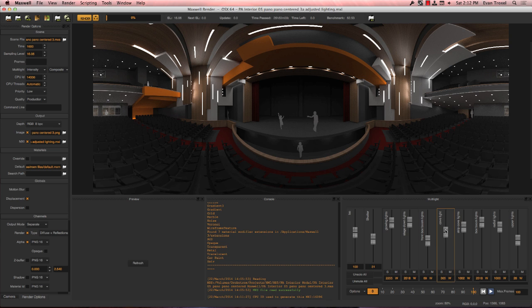And you can see this rendering, I didn't point this out before, but this is a spherical panorama. You can see it's severely warped, and you can see this seam right here matches up with the seam over here. So what it's going to do is wrap this around us like a sphere. It's basically going to spherically map this to a sphere, and we're going to be able to stand inside of it. And you can see right now I'm looking straight at the stage, which is that initial viewpoint that I set when I was in Form Z.